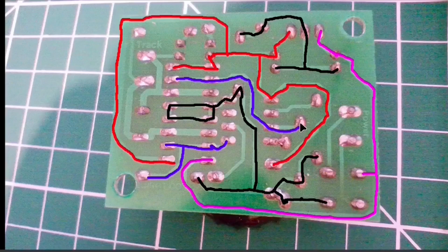So that then gives me all the information I need to try to identify this IC, because we've got where it takes its 0 volts, we've got the 5 volt connections, we've got a 12 volt connection, and we've got the inputs from the microprocessor, which would then be an enable of some form.